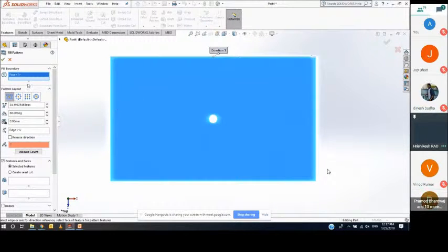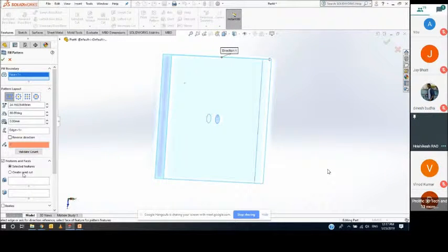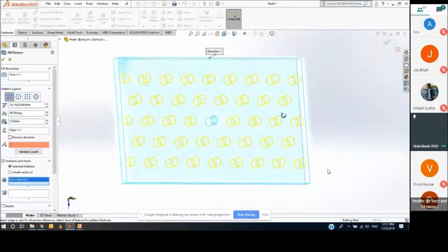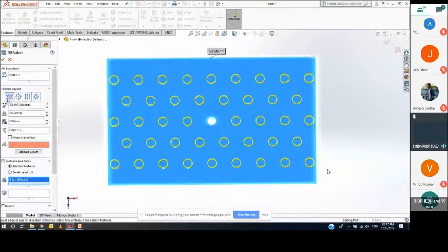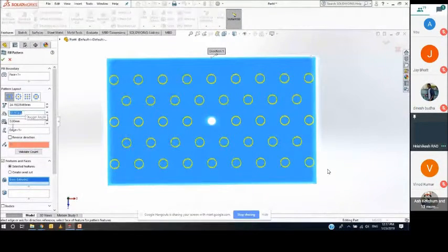Select the fill boundary, and the selected feature. So here you can see there are types of pattern layouts available. The first one being perforation, and there are a number of options available. You can set the spacing between them. You can set the angle. If I set it 90 degrees, you get a linear pattern sort of. I'll just set it to 60 degrees again.